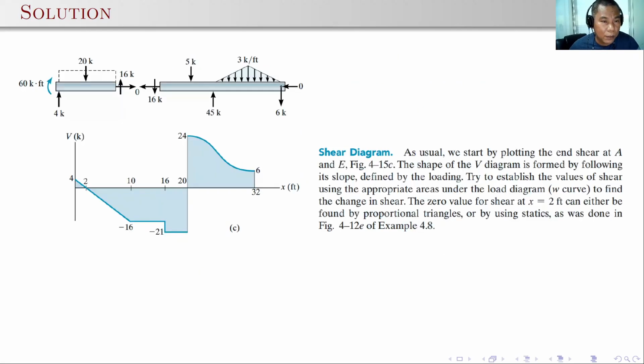As soon as you do that, you will notice that at the ends it will be useless, because the internal reactions there will just cancel out, because they are the same but in the opposite direction. So here, as you draw the shear diagram, again, draw first the shear at one end, the left end, that's positive 4, so you will draw positive 4, and a positive shear on the right hand side, that's positive 6. Okay, so you can draw that way.